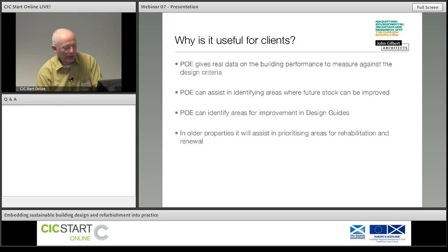The process in, you know, when can this operate? Well, for new build, we think it's ideal after about 6 months. Obviously, it is better over the heating season. And although you can't get a whole year's data for the heating of the building, you can record what the meter is at the start of the project and at the 12 months at the end of the project. So although you go and do the analysis midway, the purpose of doing that is that you can get the contractor back then and adjust anything. So you're finding out anything that needs adjusted.